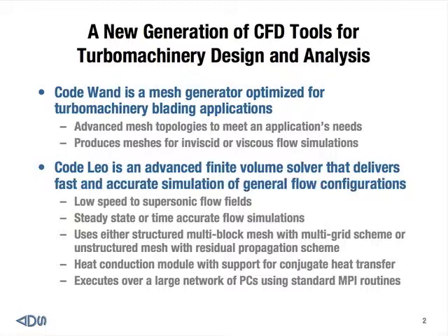Once you go beyond 3.0, we are talking about dissociation and real gas effects. So that's why the code is not applied to much higher Mach numbers, more than 3.5. And second, the code itself can do both steady state simulation and time accurate flow simulation. As the flow evolves with time, it will capture what's going on as a function of time. That's called both steady state and time accurate flow solution.